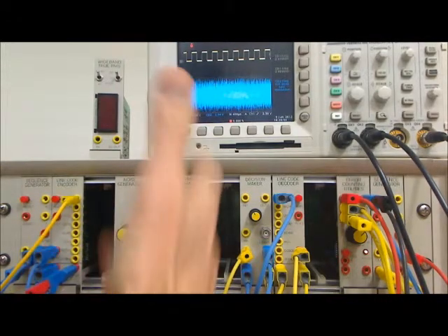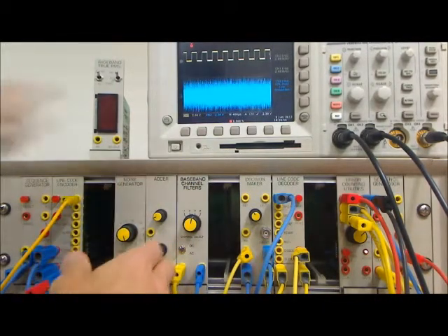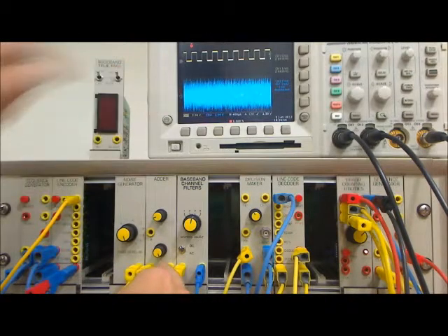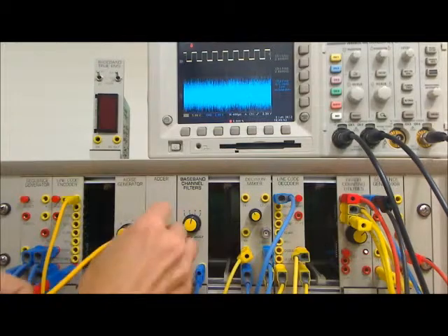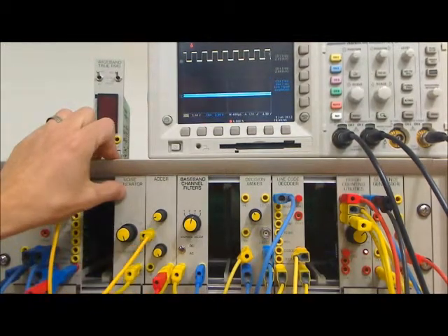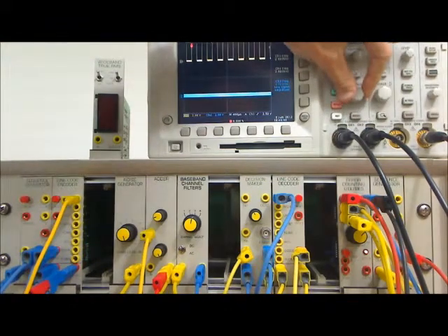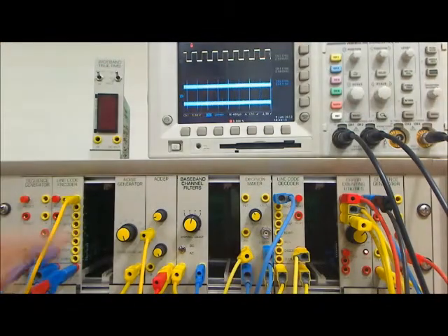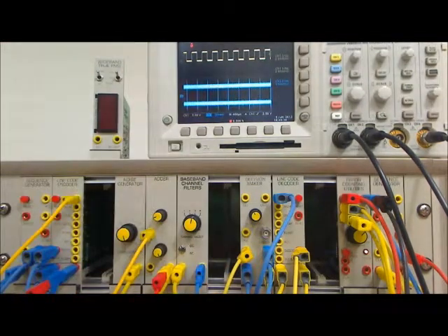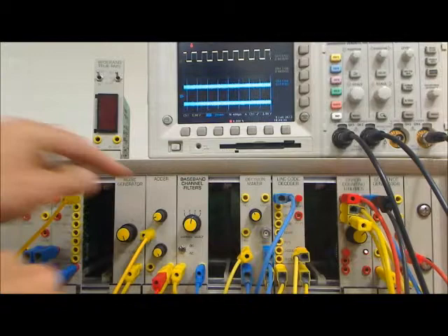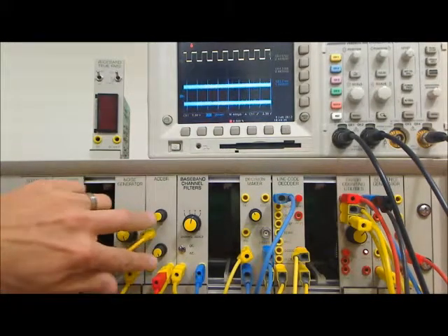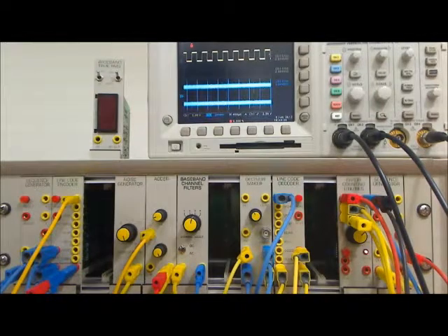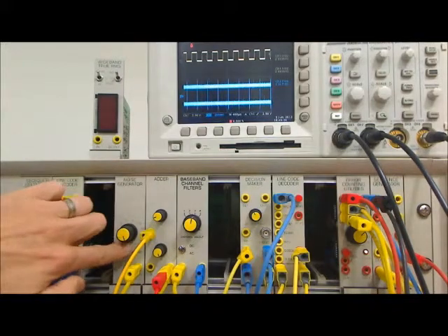If we eliminate the signal going into the adder, we will be looking purely at noise from the noise generator. If we input the signal back into the adder and eliminate the noise, and then increase the scale of channel 2, we can see that we have the line coded signal at the output. I've selected the levels of the gains at the adder in order to get an appropriate signal to noise level.